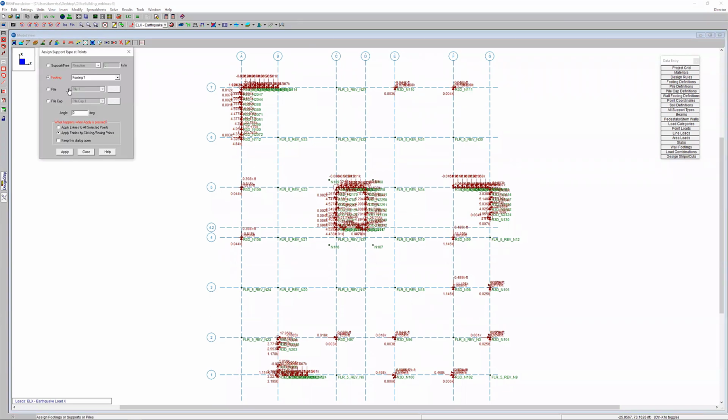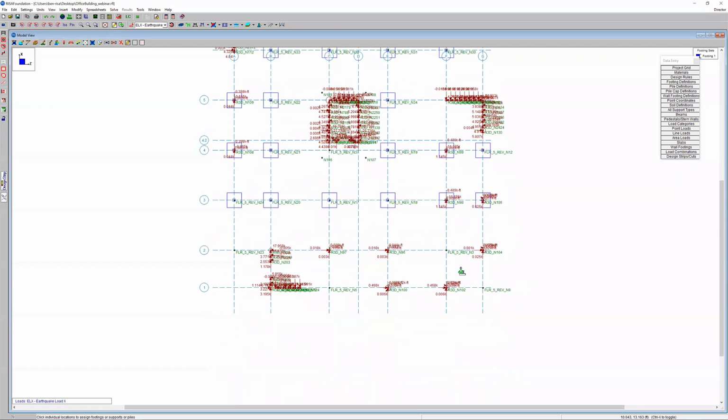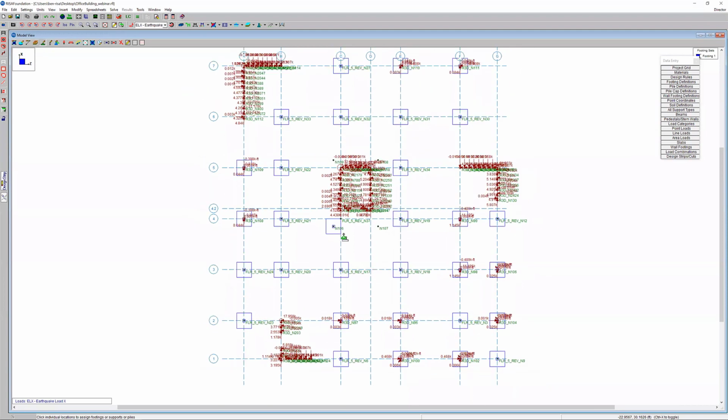And so we're going to go ahead and set that up. And we can apply different footings, but in this case, I'm just going to use that same footing. And again, this is actually an optimization, right? So we're doing an optimization here in this particular case. So it's looking at all of these, looking at this size and this criteria, and then saying, okay, I'm going to go ahead and try to find the best size footing that works for the criteria that you have, right? And so I can go ahead and create that information.